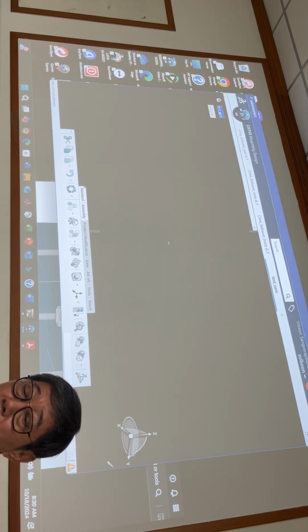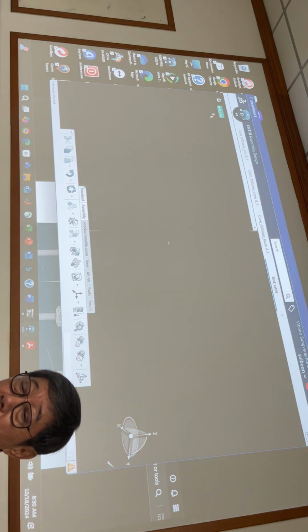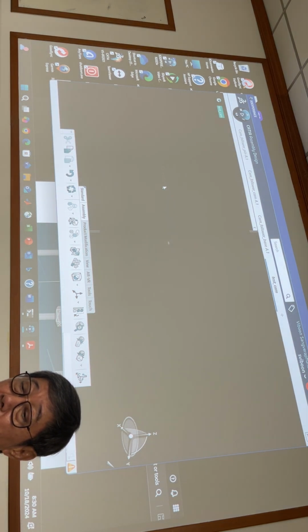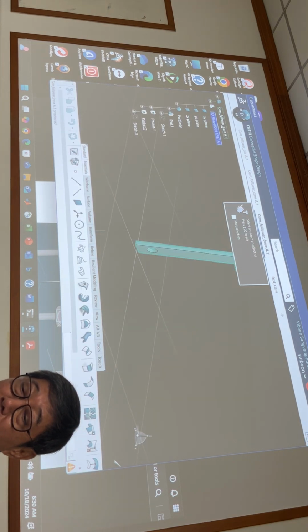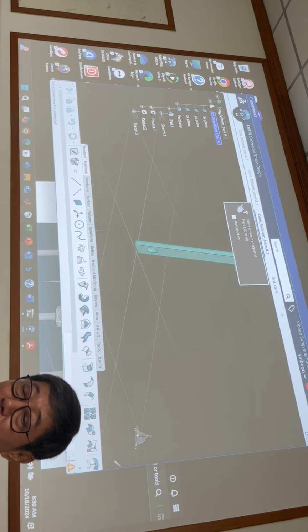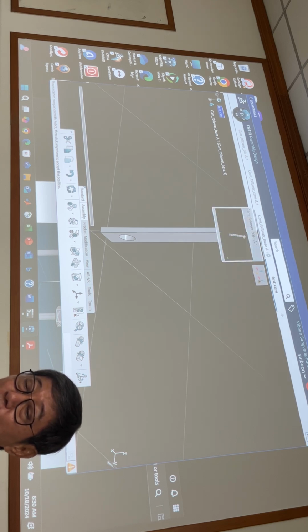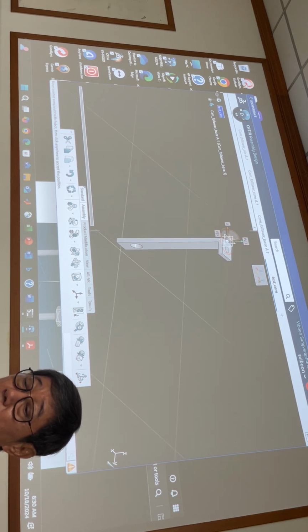So we can do this one, okay? Right? Insert. We are in assembly, right? This one. Insert. Existing product, right? This one. If you already have this one, you open this one, let's say. Right, open. You can bring in this one. See, just got it. You don't have to search for it. You just go to that one, select this, automatic insert this one. If you don't want to move, you just bring this one in like this.